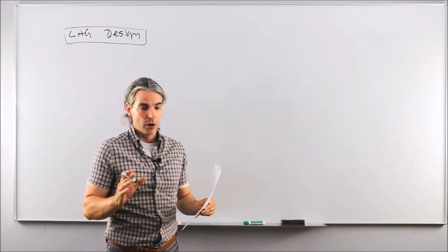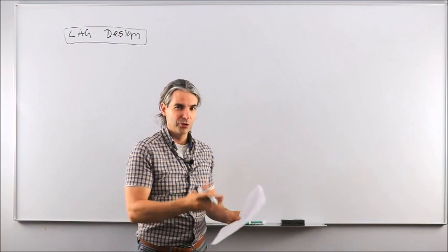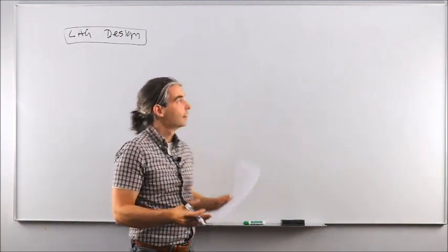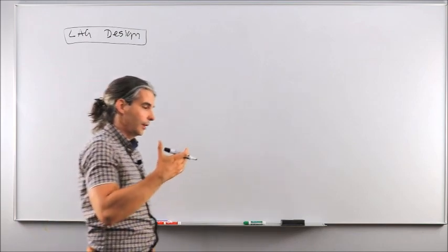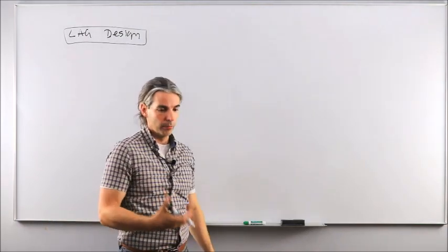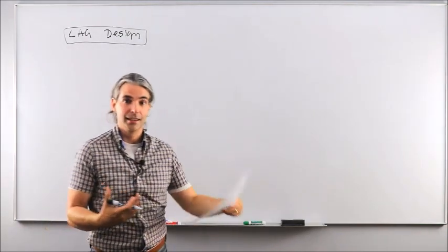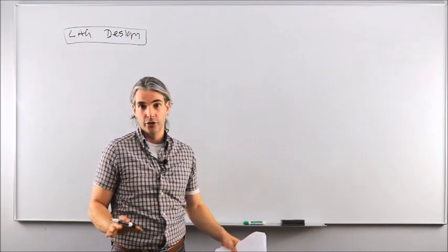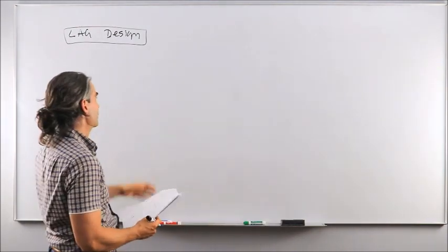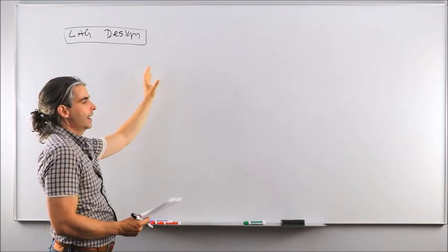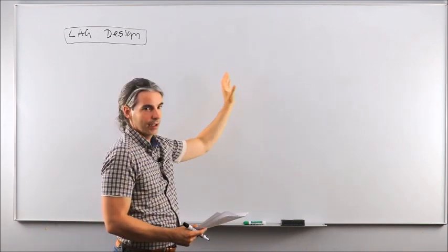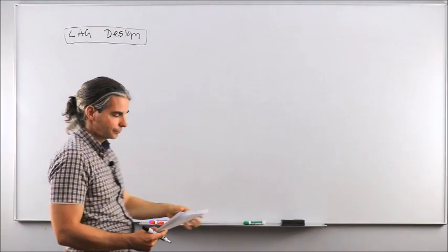So all we need to do here is to improve the steady state, which were kind of bad, by adding a phase lag compensator. If we would end up in a situation where both transient and steady state performance were not good at all, then we would have needed to design a phase lead compensator and then stack on top of it a phase lag compensator, okay?